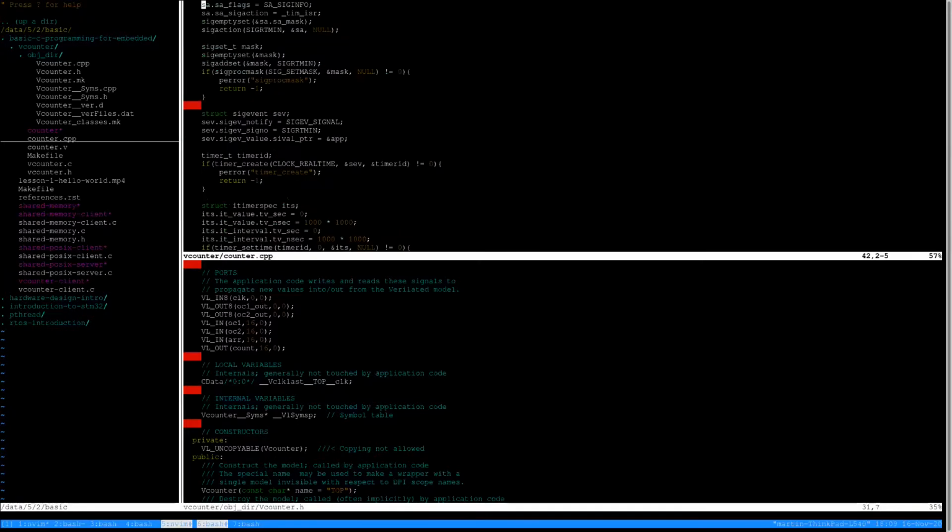So how can we use this simulated hardware and allow other applications to access it? What if we were to run this hardware as a separate process that takes care of its own timing? It has its own clock, and it just clocks the timer, and then we just use that timer as a virtual device from another application. And we can take care of the timing using Linux timers. And we can take care of the access to this virtual hardware using shared memory. And that is what I'm going to show you today.